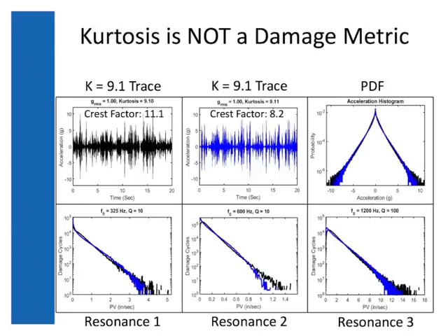And so, if you're using kurtosis in a specification, be aware that tests run on different controllers are going to do different amounts of damage to the product. And now you might think, well, if the blue trace is a typical controller and some of my vendors are using the black trace, well, they're over-testing, but I don't care. The problem is, if you have the technical know-how to build a kurtosis controller at all, you also have the ability to build this black trace.